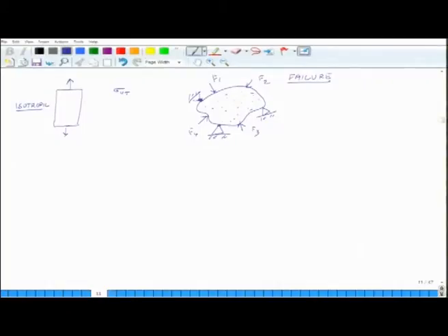Essentially, the point is that at every point in the system, you figure out what the stress is. And then at all these points, you find out the principal stresses, right. Then you want to know whether this structure is going to fail or not, and you use some of those criteria: principal stress criteria, principal strain criteria, von Mises stress criteria, distortion energy criteria.